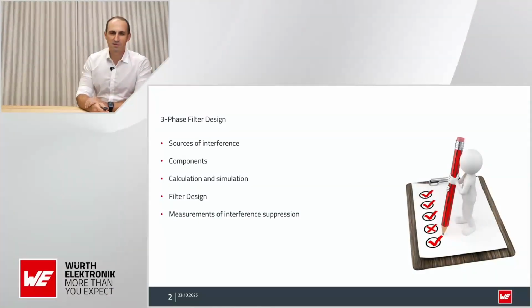Good afternoon, everybody. In this session, you will learn what the source of interference is, what kind of components you will need for a filter, and how to calculate and simulate this filter. The simulation we will do with the free software LT-Spice. We will show you how to design a filter from a schematic and layout point of view, because there are some very important topics. And of course, last but not least, we will compare the calculated, simulated and designed filter in real measurements with a real device under test.